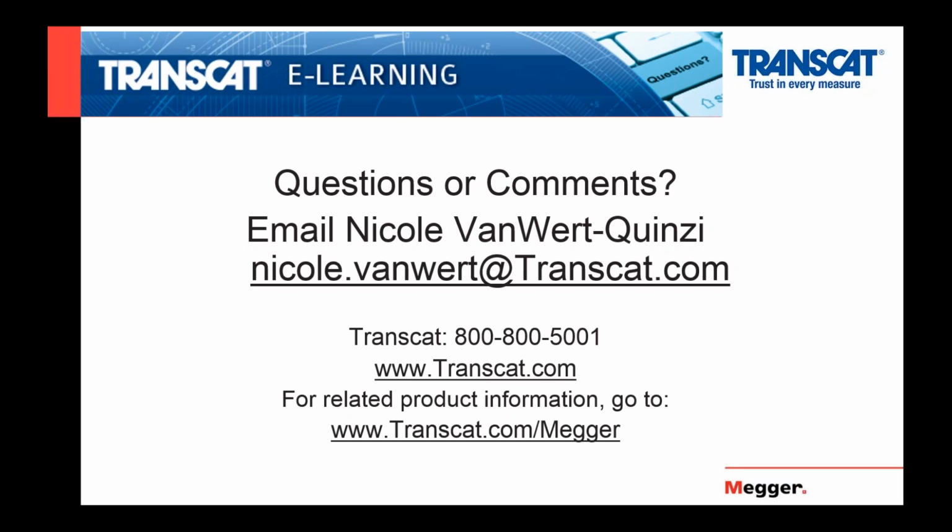Next question is, for ripple, can I measure my AC at the output of the charger? Well, remember, Kirchhoff's law, it's going to be constant throughout the entire circuit. So you can measure it at that point, provided you're not, yes, actually you can. I'm just sitting there thinking about it. You should be able to see it at the output of the charger, because it is just going through the string, so the current should be constant.